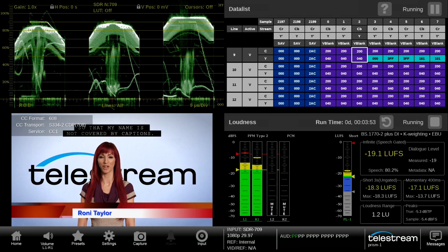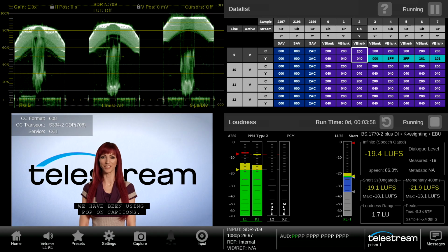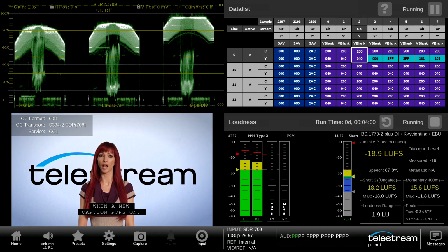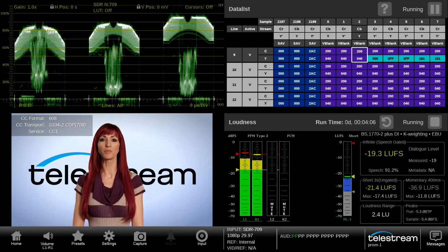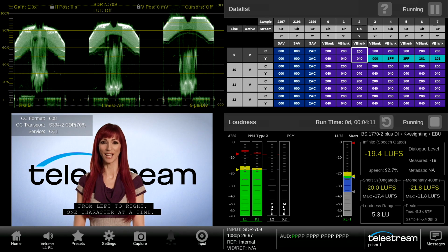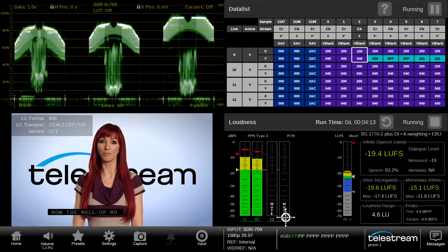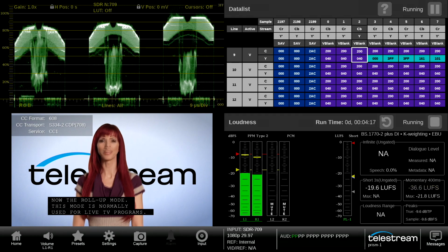Another important aspect to the configuration of loudness is how many channels are used to monitor the program. The standard default is to use a stereo pair of channels, and the green labels below the audio bars indicate those channels that are currently being monitored for program loudness. Simply select the bar groups to select the monitored channels for the audio loudness session.